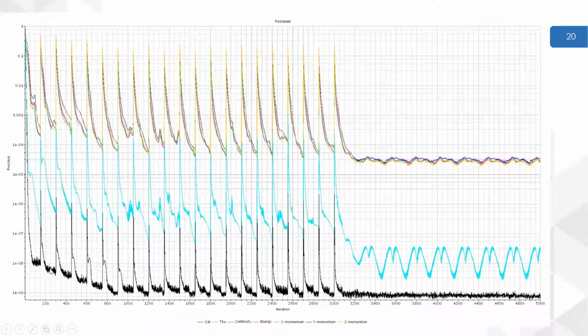And certainly if I'd done 6 mesh refinement steps, I probably would have been adequate to get where I needed to go. You can see that the residuals get to a good level. And if we let it run out from say 1,000 sweeps, just let that carry on, we'd have probably got a similar result. So it might be that these last 15 or so mesh refinement steps weren't needed.